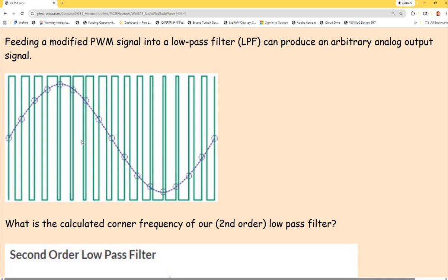And you can use that number as a duty cycle, as a duty value for your PWM module, and directly throw it to the speaker, and it's going to play the audio for you. Do you know what I'm saying? So you sampled it, right? You sampled it, and that sample data falls into the range of 8 bits. And that becomes 0 to 255. No problem on that, right?